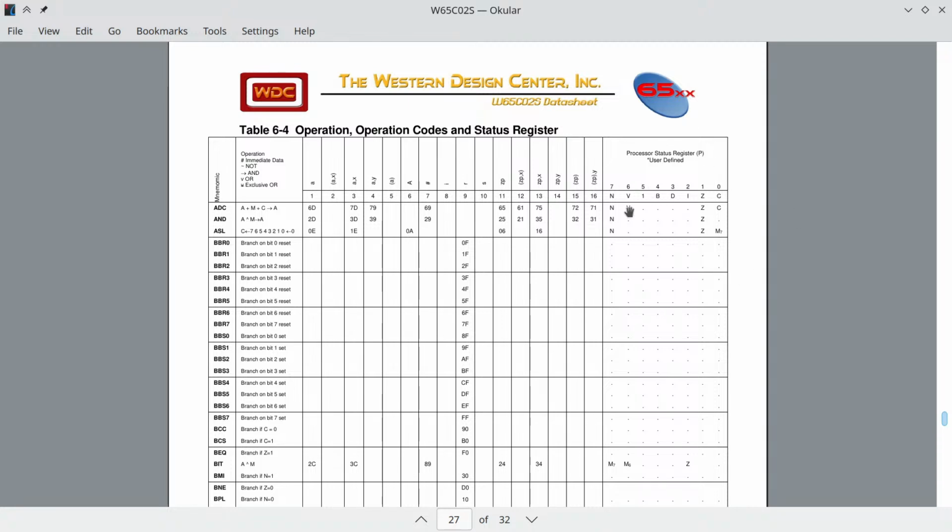So if we look at the condition codes, we can see that the negative flag gets whatever was put in bit 7. The zero flag gets the condition of the register after the shift. And the carry gets whatever was in bit 7 before the shift. So negative gets bit 7 after the shift, and the carry gets bit 7 before the shift. Cool. Except what you will notice here is that this doesn't work on the accumulator like we're used to.